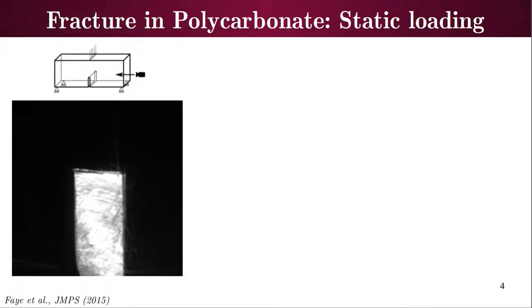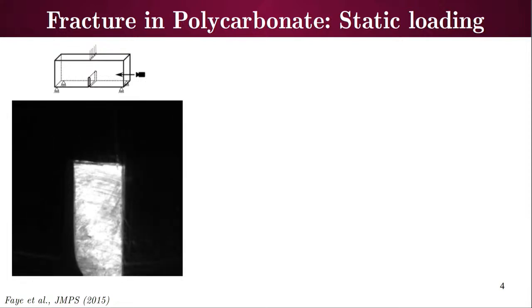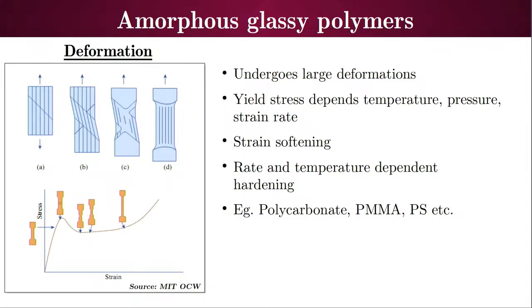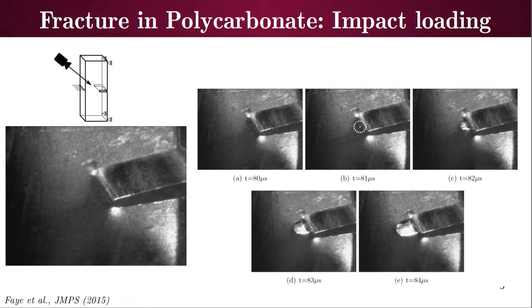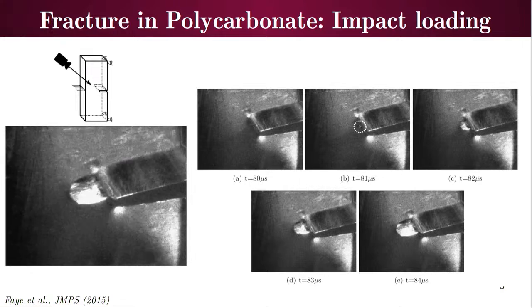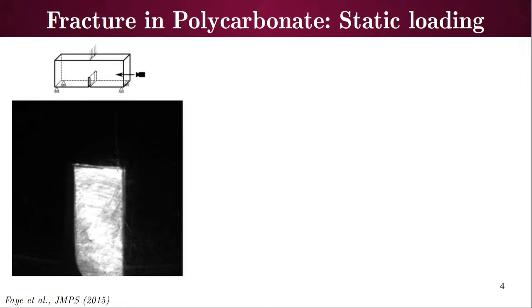No, the middle section is the weaker section. It is ahead of the notch. There, the stresses are high. So it's not the corners, because usually it's corners. Oh, you mean along the thickness? If you go to the picture before, perhaps the other way. Oh, okay. That one, yes. In fact, you see, it starts in the middle, and in fact grows out. Why doesn't it start at the corners also and go coming in?